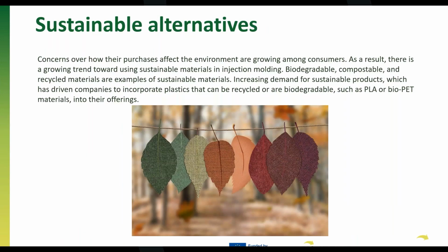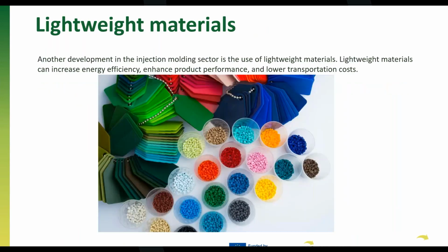It's more a matter of small modifications in the mold to adapt for the material, and in the temperature profile to adapt for the needs and avoid degradation of the material in the screw, so that we obtain a quality part in the end. And of course, also in the design, keeping in mind the final mechanical properties that our material will have. So mainly it's quite similar, but only these points about the behavior of the material are the ones that we have to keep in mind if we want to produce a good quality part. In the next slide, the other alternative is lightweight materials.